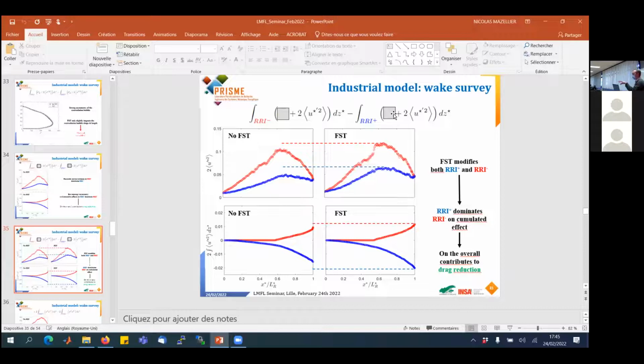They have shown that if you don't pay too much attention to the way you solve the flow very close to the wall and close to the front, then you may change whether your bistability is present or not. Here we are using RANS close to the walls, because the hybrid approach is RANS where it's expensive and LES where it's not. So I think we miss the problem anyway.